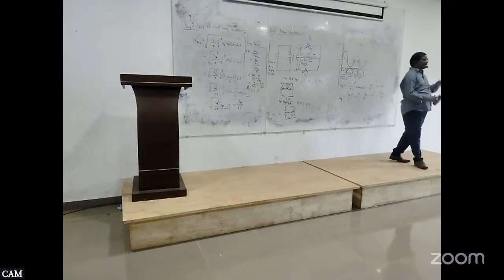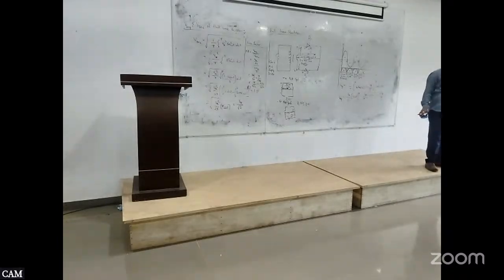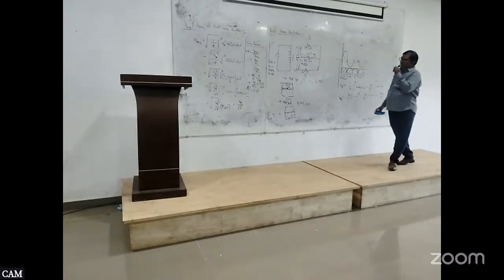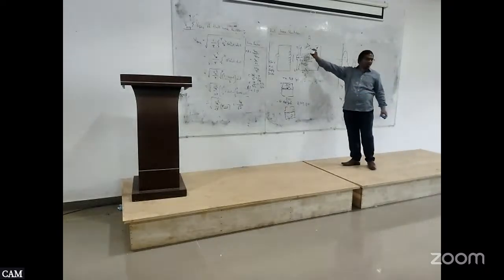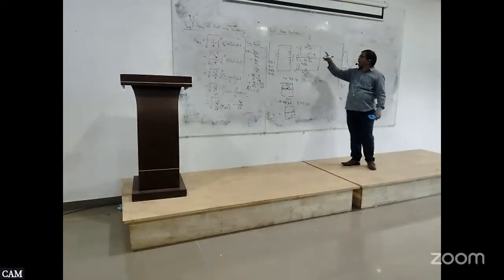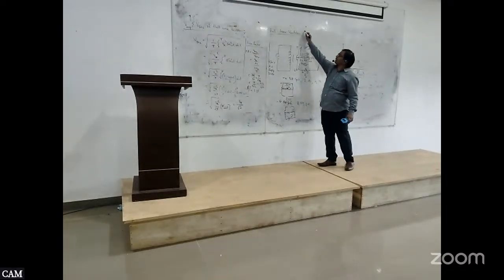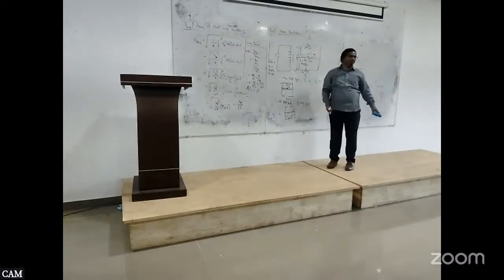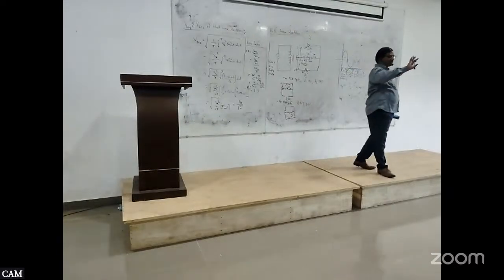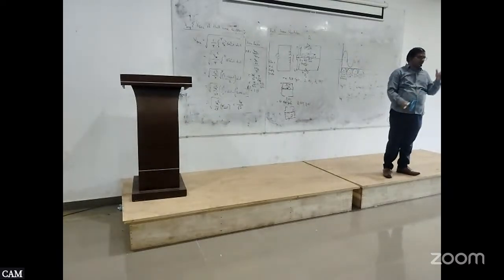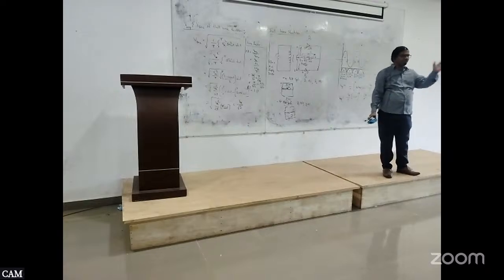That area can be removed by adding a filter. So, the ripple filter. Okay, it is a filter. We can call this capacitor a filter now. Half wave and full wave rectifier with filter. By adding a capacitor across the load, the circuit becomes a rectifier circuit with a filter.